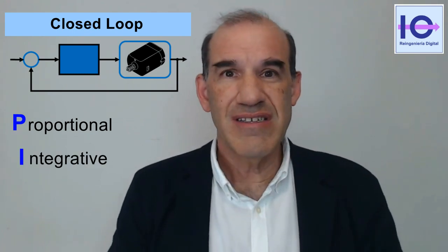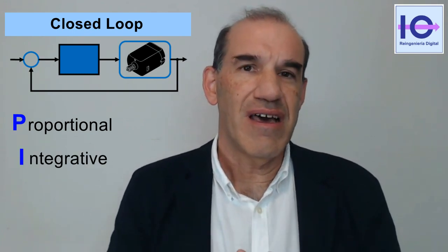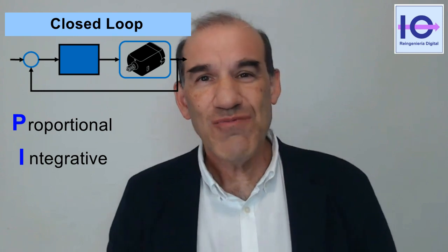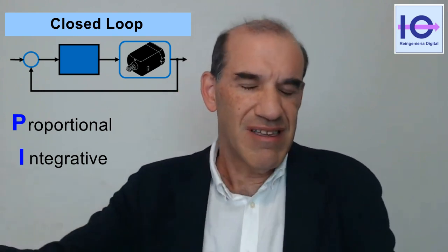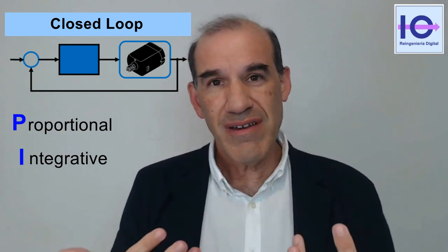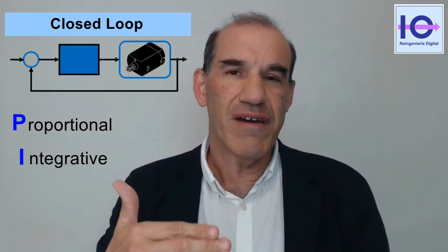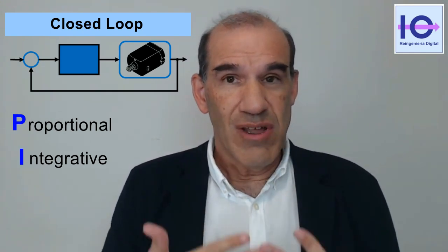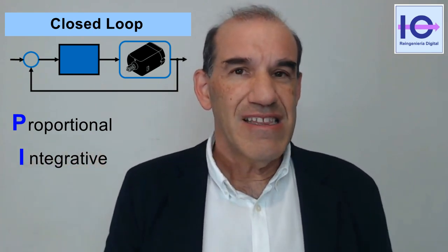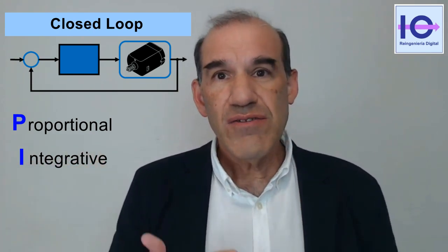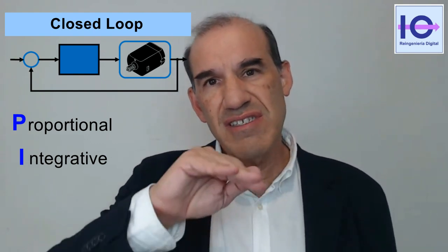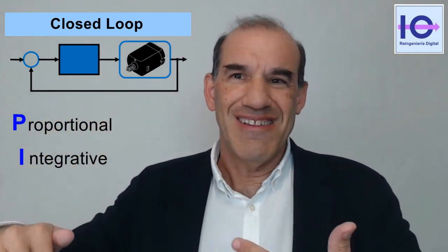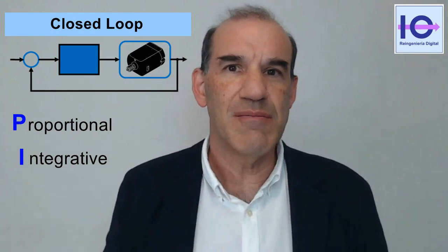The second component is the integrative component, the I component, and it applies an integral. As you may remember, an integral is a kind of summing up, in this case, of error. So really what the controller is acting on is the cumulative error. The integral component allows us to eliminate that steady state error, but tends to exaggerate the correction, and due to inertia phenomena, it's not strange that it exceeds the desired value, although in future time it arrives at the desired value.